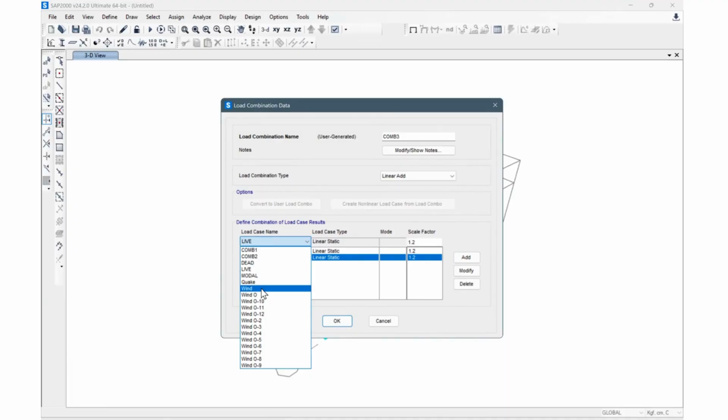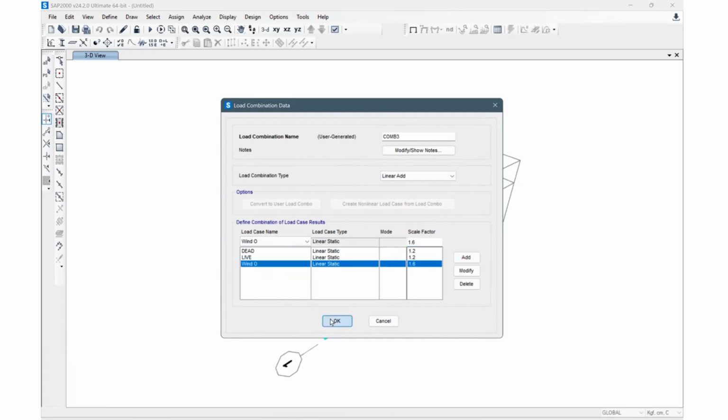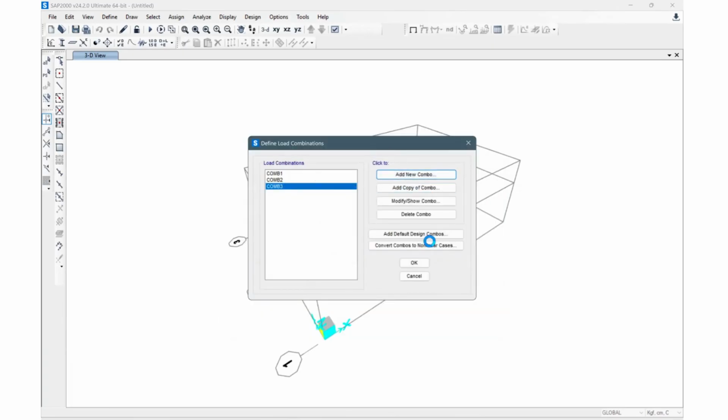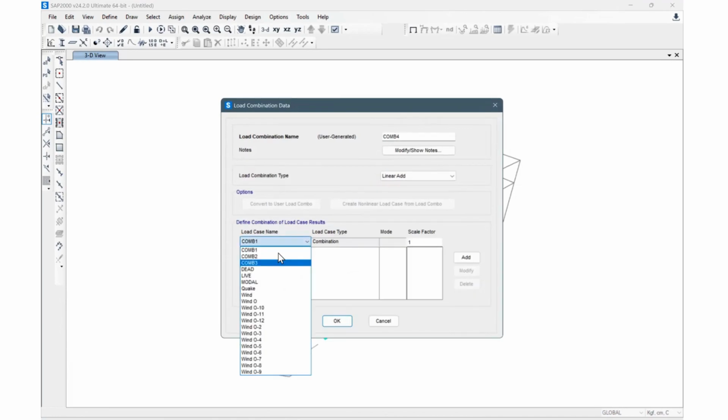So if you use the manual method, applying it by yourself, you should not use the other one. If you use the auto load, you should not use the manual method. So it's up to you. Let's say I just use the auto one. I'm gonna use this to be 2.6. Okay. And next, for earthquake, we can define the same.